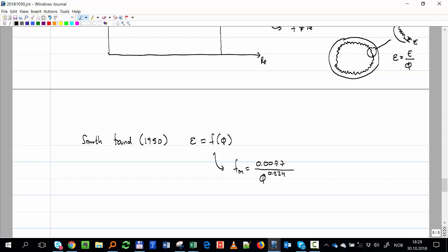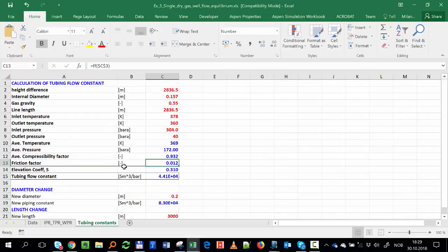Finish. I don't have to calculate Reynolds, I don't have to calculate density, I forget about all of that issue, right? I just use a factor that depends on the diameter. And that's very nice with gas. If we had liquid, we would have to calculate Reynolds and do the whole process. So I think that's the expression we have here in the exercise. Its friction factor is here, FF.